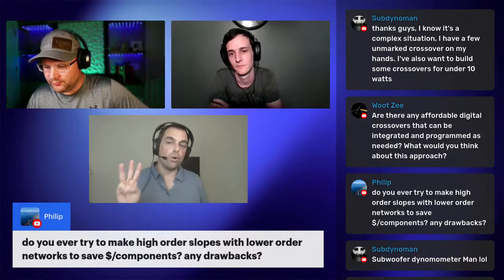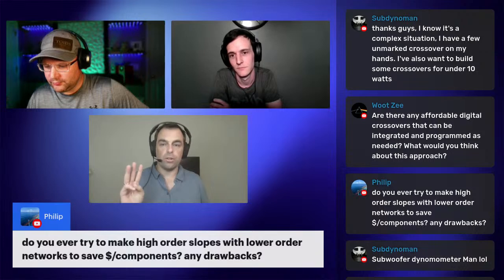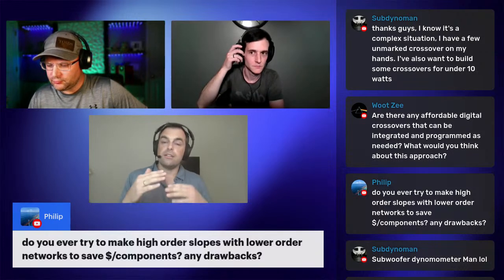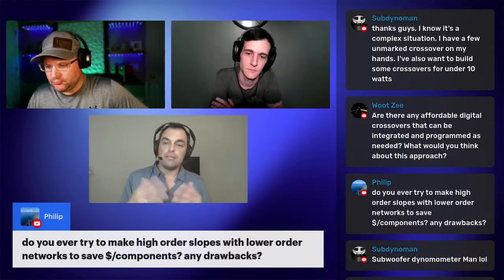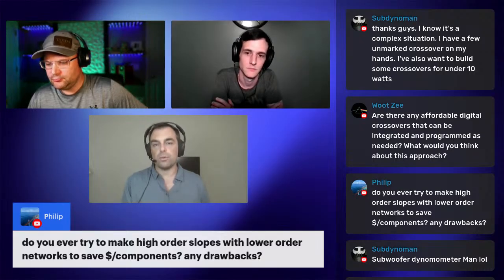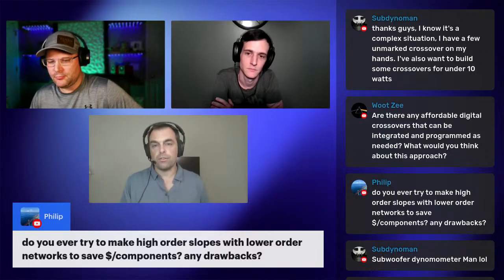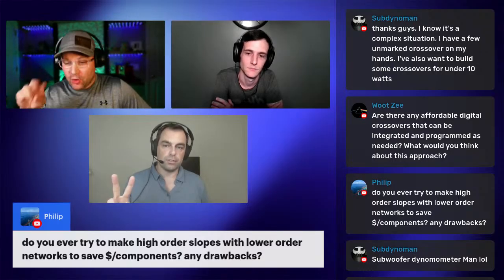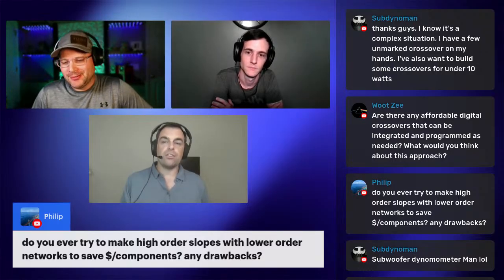That's a third order acoustic roll off. Okay, let's go to second order on the tweeter. Now we're getting a 12 dB transfer function on a 12 dB acoustic slope, which gives us 24 dB per octave roll off acoustically. Now we have a fourth order acoustic roll off on that tweeter, and we've only used a second order crossover filter.